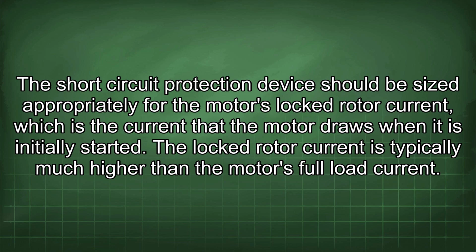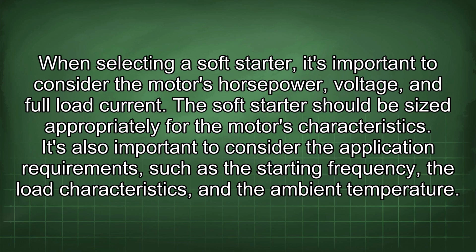The locked rotor current is typically much higher than the motor's full load current. When selecting a soft starter, it's important to consider the motor's horsepower, voltage, and full load current. The soft starter should be sized appropriately for the motor's characteristics. It's also important to consider the application requirements, such as the starting frequency, the load characteristics, and the ambient temperature.